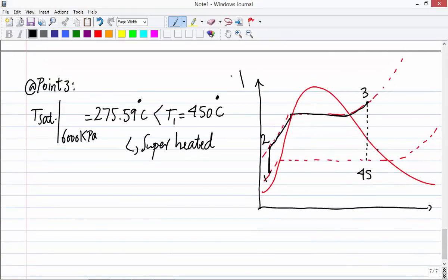This is temperature versus entropy. So we will end up at a higher entropy, like that. There. So we have a little bit of deflection of the isentropic vertical line. So here would be 0.4 actual, right? And then in the condenser, we have the phase change and the subcooling here. That's it.